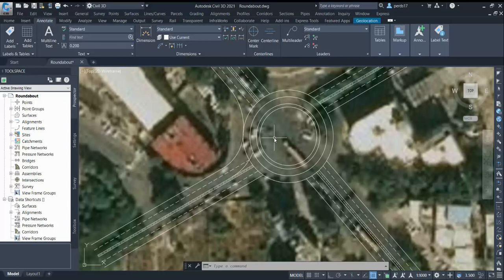Like I said, our approach width is 3.5 meters, and at the entry we are increasing our width because we have a sharp entry radius, and to move the vehicle very smoothly we have to give some extra width. So we opted for 4 meters. We are transitioning from 3.5 to 4 meters, so we need to check that this transition does not go in very sharply. It should give some distance, and that will be decided based on your flare length.